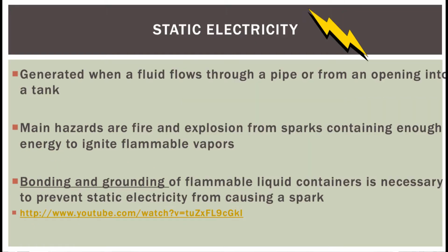Can't stress enough that a flammable liquid will generate its own static electricity when it's sloshing around in a tank or being transferred into a pipe. It's because the electrons are lining up. And it's very important to ground and bond material when you're transferring flammable liquids.